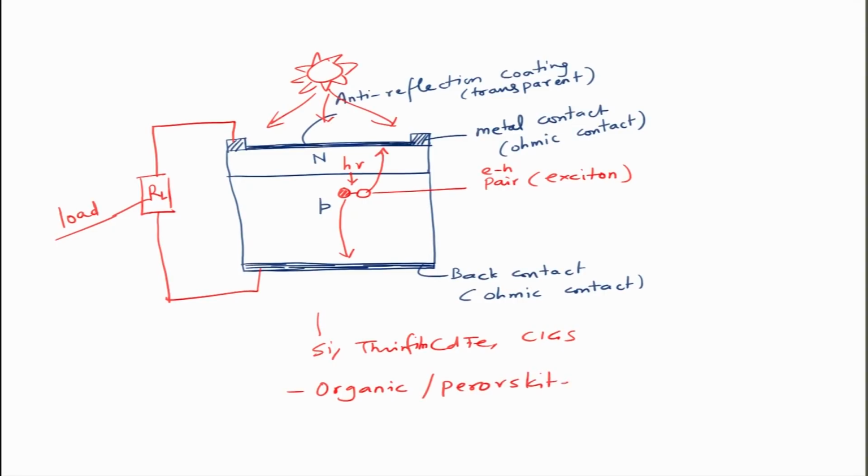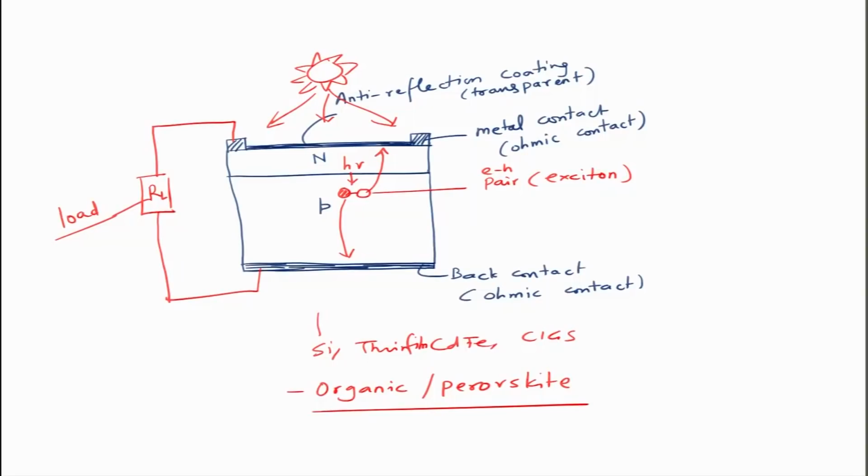In this case, although you have bilayer solar cells also, the typical architecture is where P and N materials are mixed together with each other at a microscopic scale, and in between the contacts there are also carrier selective coatings which preferentially allow certain types of carriers through, so holes will go preferentially to the anode and electrons will go preferentially to the cathode. So, this is a typical device architecture that we see for a solar cell.